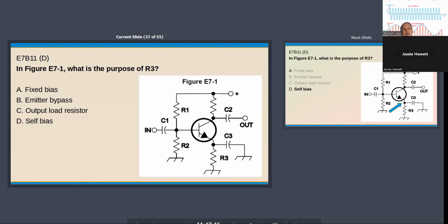So if you look in the data sheets for transistors, they'll usually show a bunch of lines for different values of base current and what the collector current is for that. So when you draw the load line through there, you pick the point you want and figure out the proper amount of bias for it.